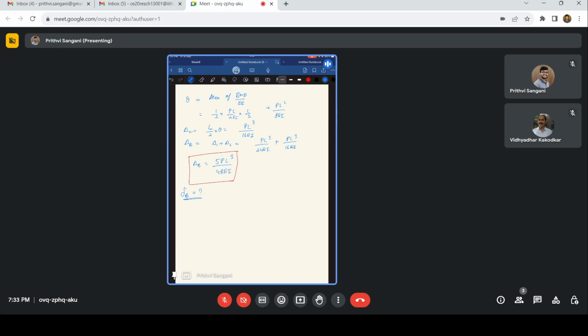If you have two boxes, like if this is your portal frame, you have three unknowns, three redundancies here and three here. So you have 3 times 2, that is 6 here. 6 plus 6, 12.